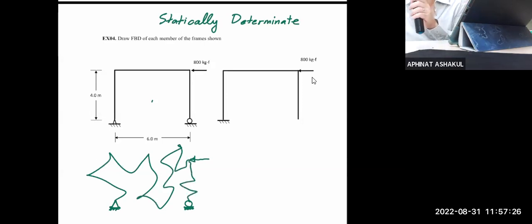Would the reactions change? No. Good. So it doesn't matter what I have in the middle. The reactions are just what make sure that your system will be held in place. So don't get confused when you have a crazy looking frame, because it doesn't change the reactions as long as you are in statics.